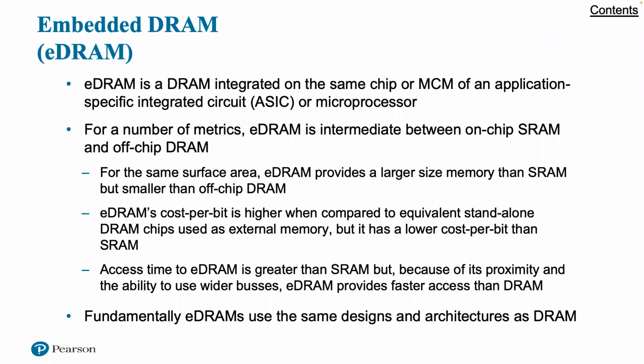Okay, next we'll talk about embedded DRAM, EDRAM. An increasingly widespread technology used in the memory hierarchy is the embedded DRAM or EDRAM. EDRAM is a DRAM integrated on the same chip or MCM as an application-specific integrated circuit, or ASIC, or microprocessor.